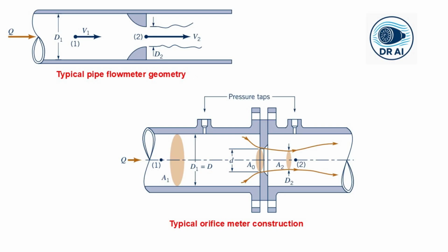First, the flow does not always follow the geometry perfectly. In an orifice meter, the fluid has to make a sharp turn and it separates from the wall, creating a vena contracta, a point where the flow area is actually smaller than the hole you drilled. Secondly, there is always some head loss due to turbulence and friction. You cannot calculate these effects from theory alone.